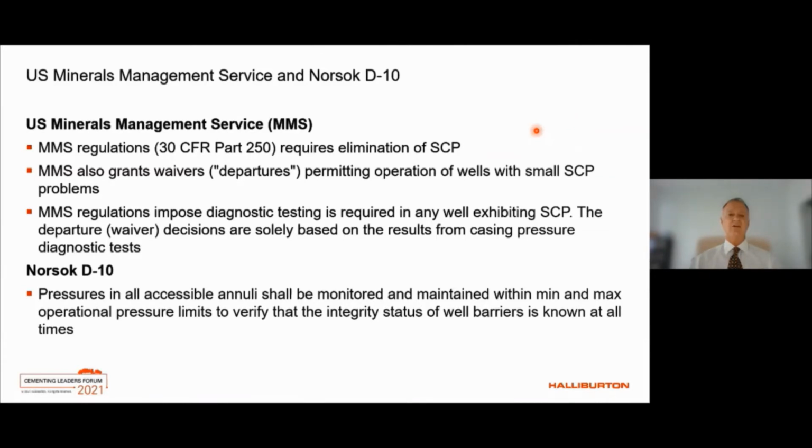The regulatory authority in Norway, NORSOK, published a document called D10 that states all accessible annuli should have designated minimum and maximum operational pressure limits, and they should always be monitored.